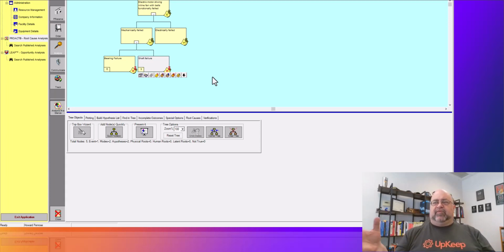And I've done this before in a couple. I've gone in and I've said, okay, we take a look at, say, a seal failure, and I've got a long line of conditions that could cause a seal failure. And I remember saying, you know what, there's some changes with the lubrication, or there's changes in the material being used. Why don't we just do a quick check on the oil? So I added one. It was oil, and we're looking at a good solid type of seal material.